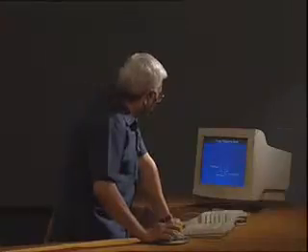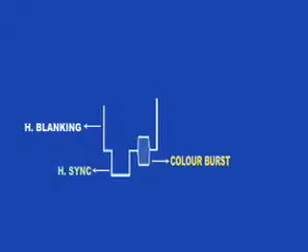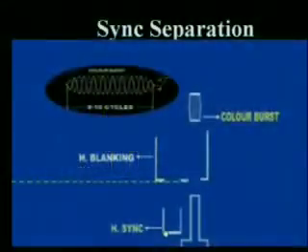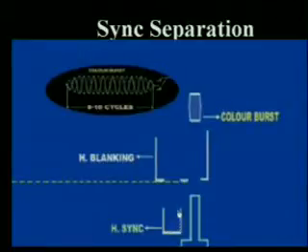And this black burst, which contains the horizontal sync, is needed for the horizontal oscillator. But the horizontal oscillator will not accept the horizontal sync in the same form.